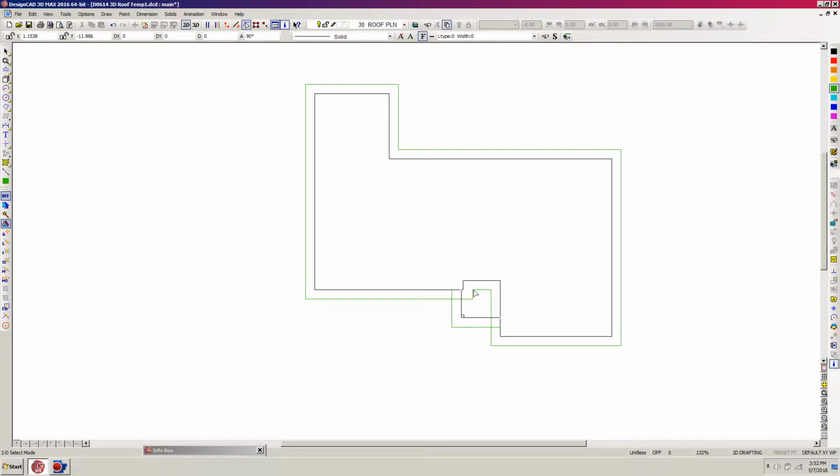So all this little stuff in here we need to get rid of. I'm just going to select the line, go up to it, and hold down just the Control and it turns to scissors, and I left click and it cuts the line. So now I can hold Control Shift, and you'll see my cursor turns to a minus, and I just click on each one of these that I want to get rid of. Okay, so those are good.